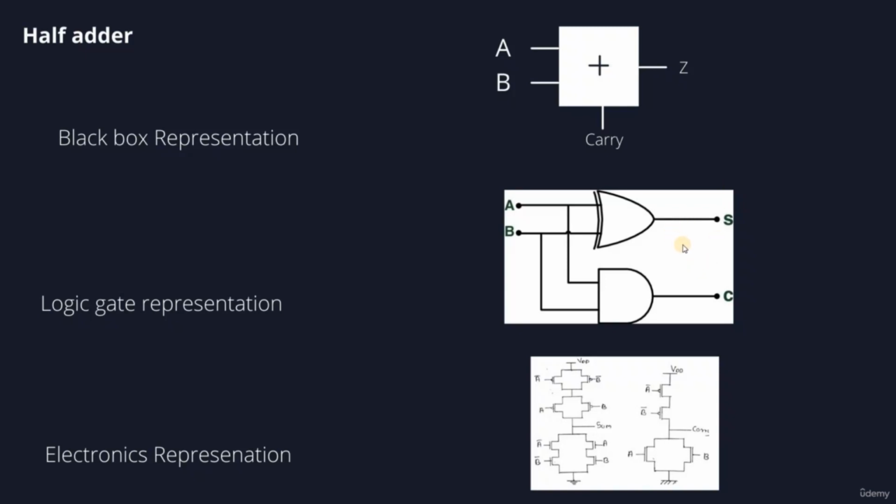Now we can create a lot of arithmetic and a lot of mathematics just using this simple circuit. Now, if we open it up and see what the electronics looks like inside, we're going to see transistors that are connected in this way. So this side right here, the S, looks like this. This is the sum, this is the A and the B. Same thing here. If you look at the carry, its circuit looks like this, right? So right here, if we have some electronics and we connect it exactly like that, and we have inputs A and B, you're going to have an adder, a circuit adder, which can later be used to create a real calculator, which is the basis of the CPU. We're going to see that also later.